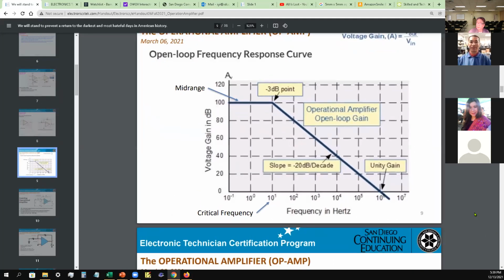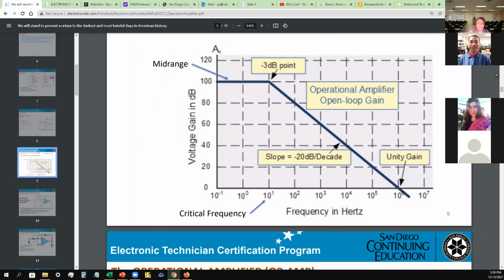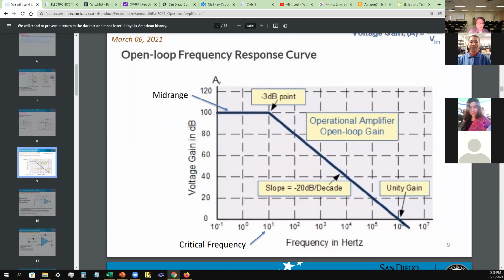When you're looking at the picture, how many students understand? Okay, you can see that's what they're using: open loop gain 100. And this is the bandwidth, and the bandwidth is only 10 hertz. Right here, that's only 10 hertz. We cannot use a bandwidth of only 10 hertz.